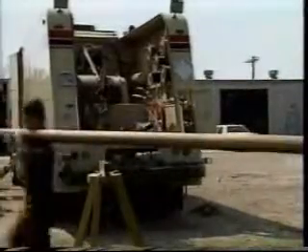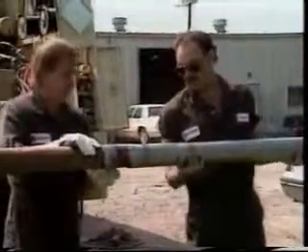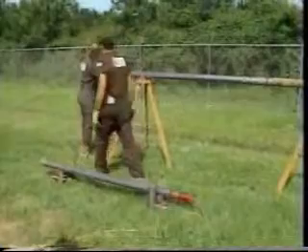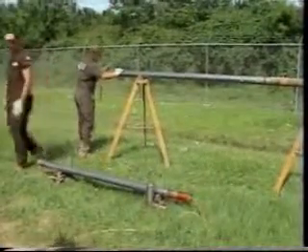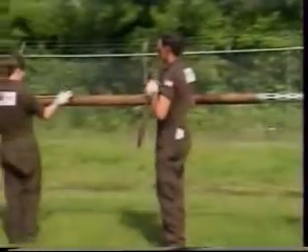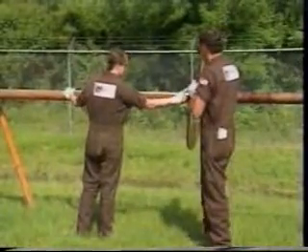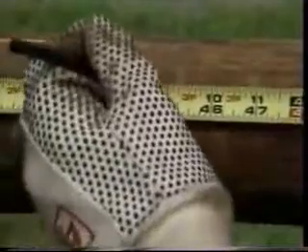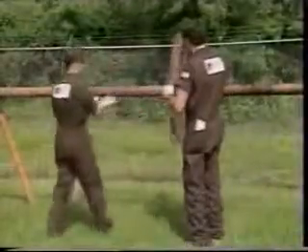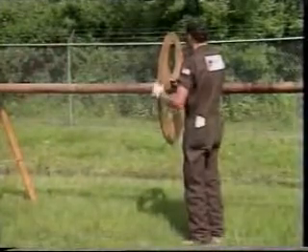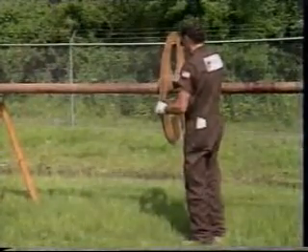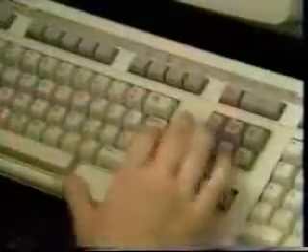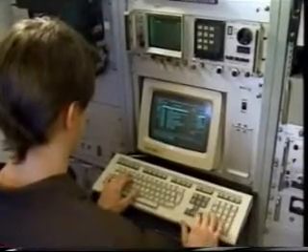Since the measurement is one of conductivity, the tool is first placed in a zero conductivity environment and should measure zero conductivity or infinite resistivity. Now, when an artificial formation of known conductivity is introduced and placed about the tool, sensitivity can be adjusted to measure its value. After these two endpoint measurements are made, the tool response will be able to reproduce conductivity and inversely resistivity measurements found in most formations.